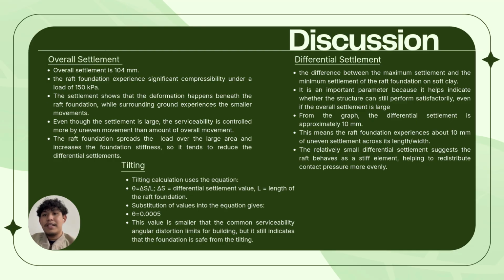Firstly, about the overall settlement. Overall settlement is about 104 mm. The raft foundation experienced significant compressibility under a load of 150 kPa. The settlement shows that deformation happened beneath the raft foundation while the surrounding ground experienced smaller movement. Even though the settlement is large, the serviceability is controlled more by uneven movement than the amount of overall movement. The raft foundation spread the load over a large area and increased the foundation stiffness, so it tends to reduce